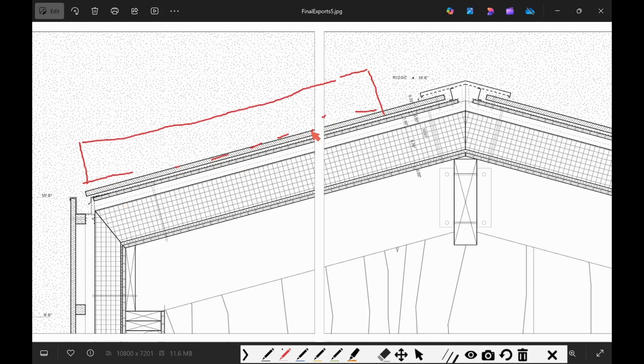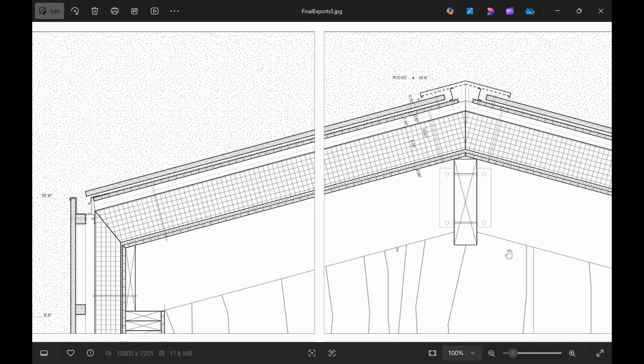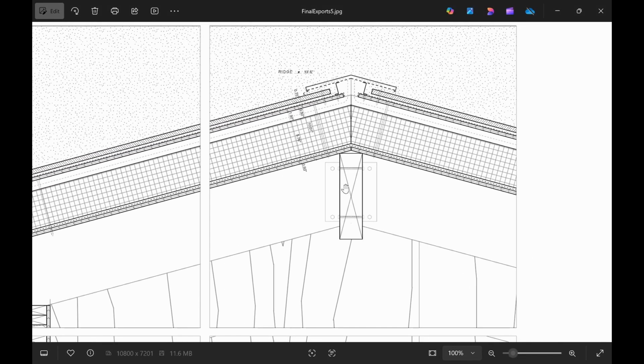If not, this is just going to have so much water on here, and then when nighttime hits, it's going to freeze, and it's going to freeze in here as well. It's going to build up in here, and when it freezes, it'll expand, and that's how you get a lot of water damage in a lot of places. Yeah, but that's the actual detail assembly.